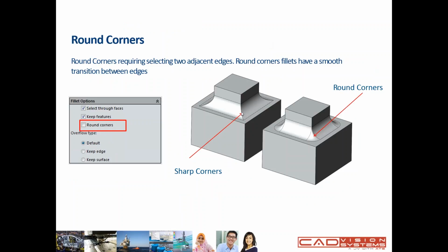From the perspective of manufacturing, sharp corners are something that we always need to avoid, because it is not an easy job to manufacture in this way. So you can make round fillets for that area so that it looks better and is easier to manufacture, because you have a smoother transition between the fillets and the edges.